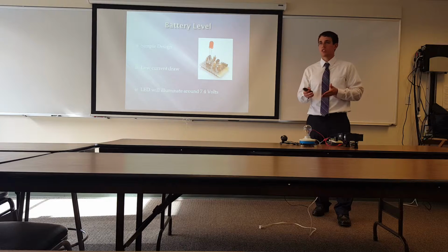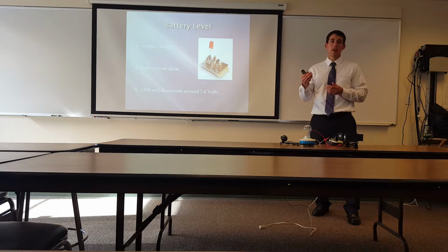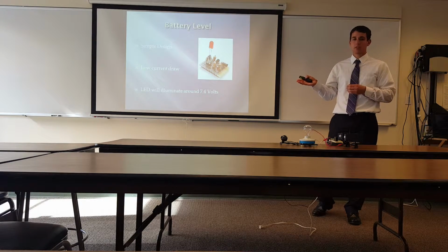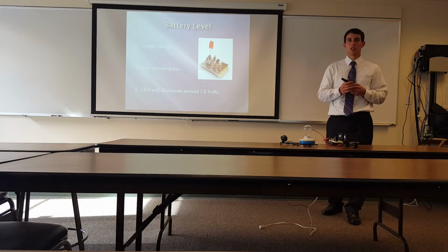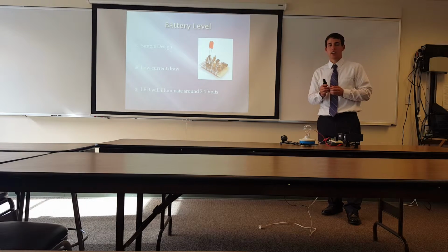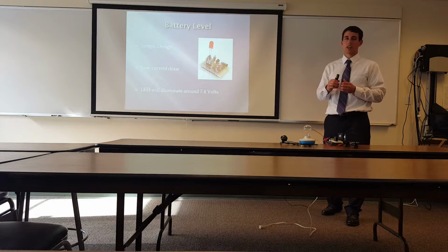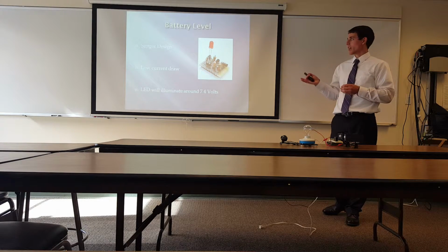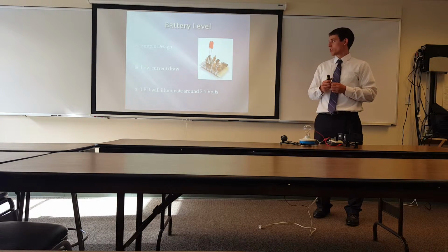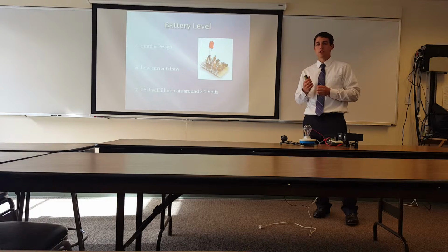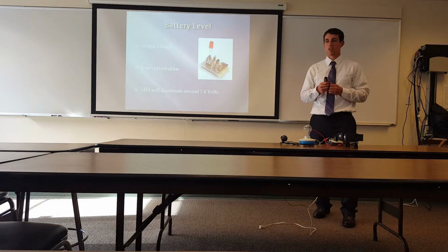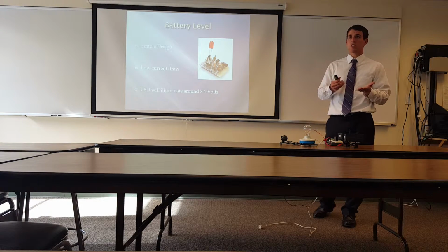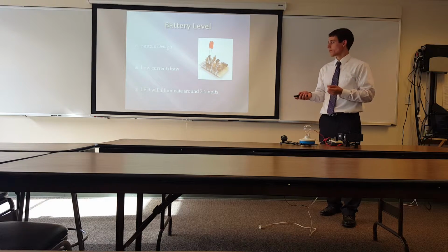So, since this is a wireless system, I wanted to implement a battery level indicator. The first battery level indicator that I designed drew too much current, so I had to scrap that design. This is a simpler design than I originally had, and I chose this over the other one because it has a low current draw. So less current equals longer battery life.